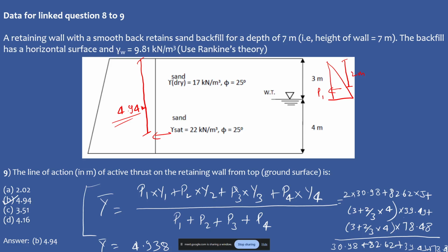Yes, the formula will take care, but I'm trying to understand the free body diagram of the soil medium, since the wall is moving in that particular direction. The Ka and Kp will take that movement of the wall into account, and we don't need to show it in the stress diagram.